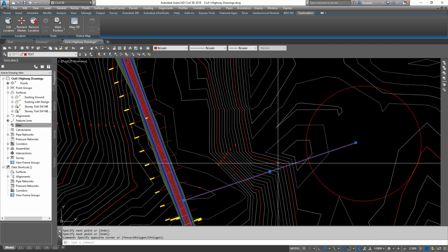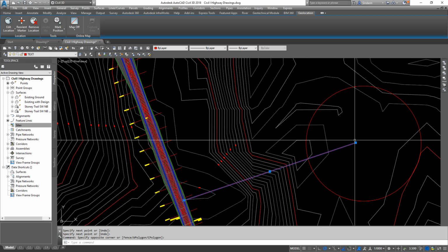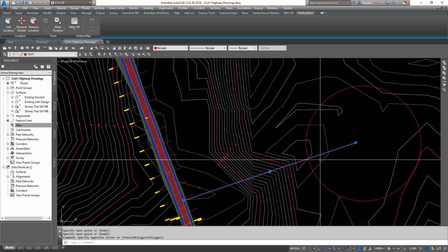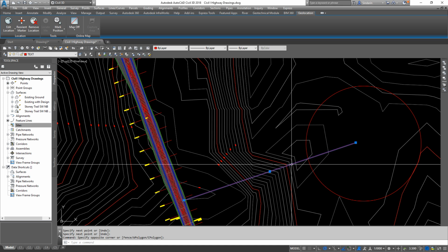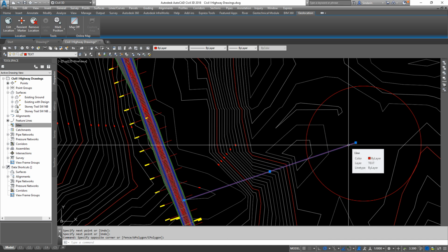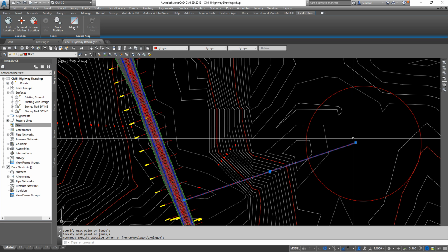Now, because of this big slope, we would just follow along with the slope. It'd be greater than 1%. But then we get down here, we'd have to go back to 1%. So whatever that ending elevation is of this line, that is what your high water level would be, or just below it, if we want to add some freeboard. 0.5 meter of freeboard, 0.6 meters of freeboard.